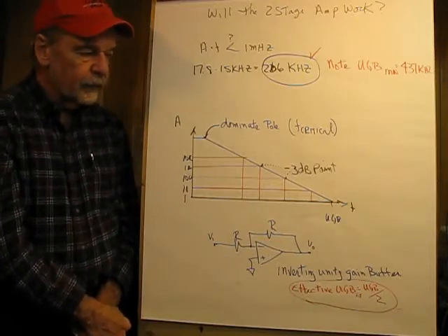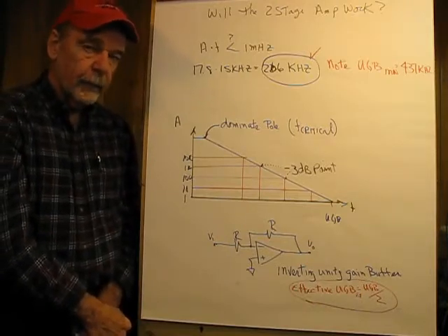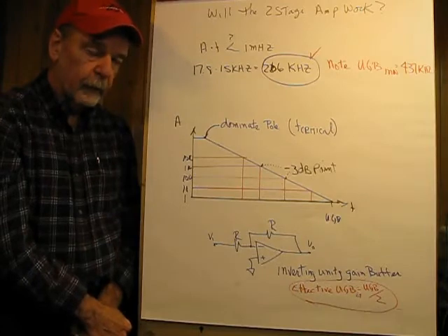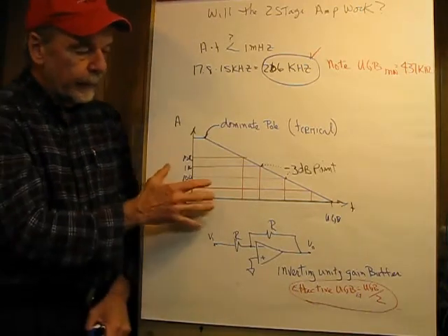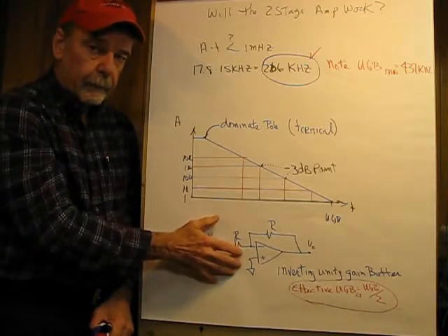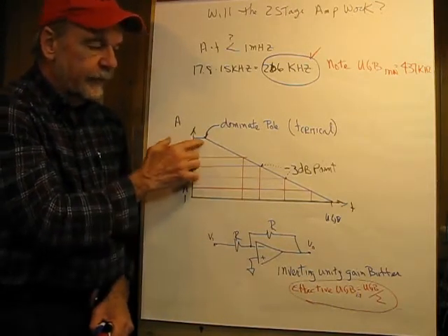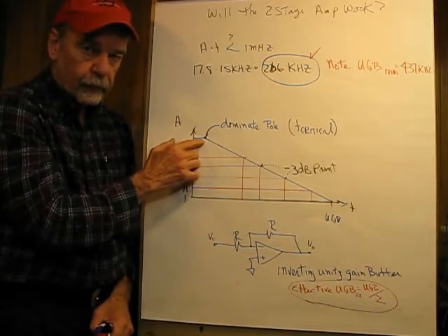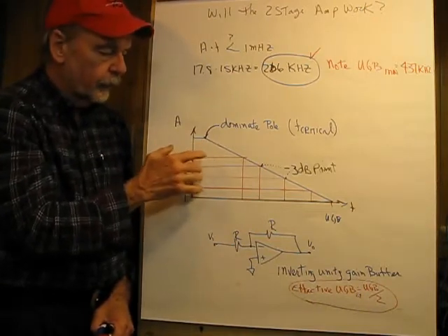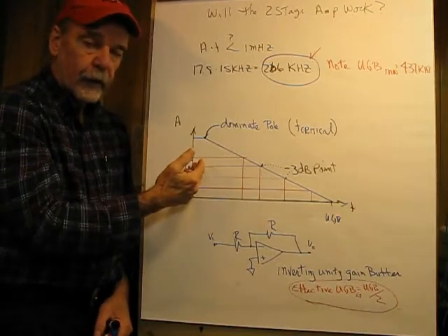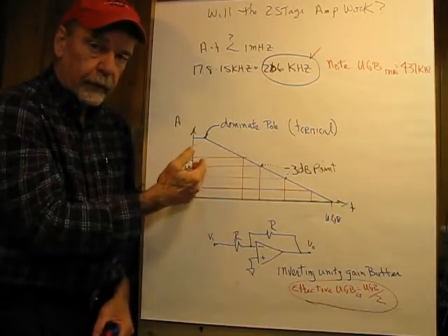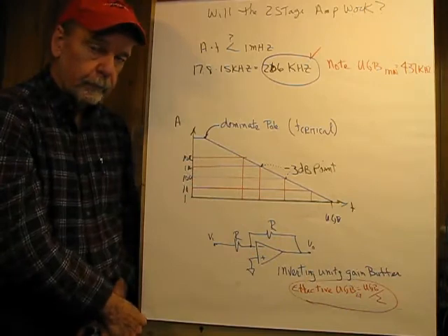And what that means is that the manufacturers place a fairly large capacitor, a nominal 30 picofarad in the case of a 741, at a critical node inside the op-amp, and what that does is it dominates the frequency response. In other words, we have, say, an electrical circuit with numerous R's and numerous C's, and each one can produce its own critical frequency.